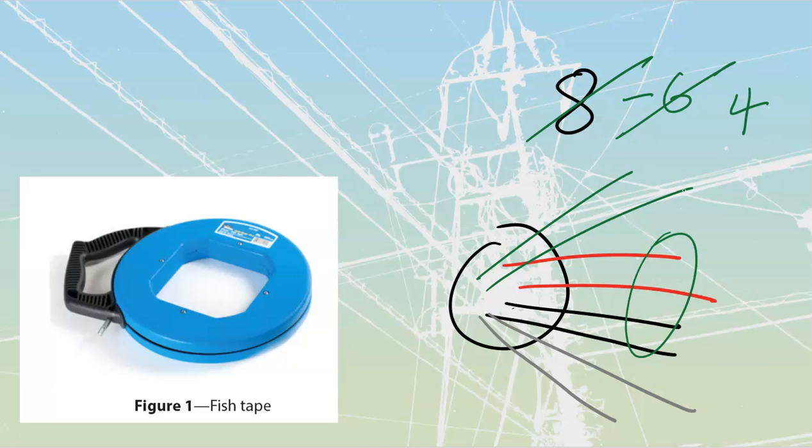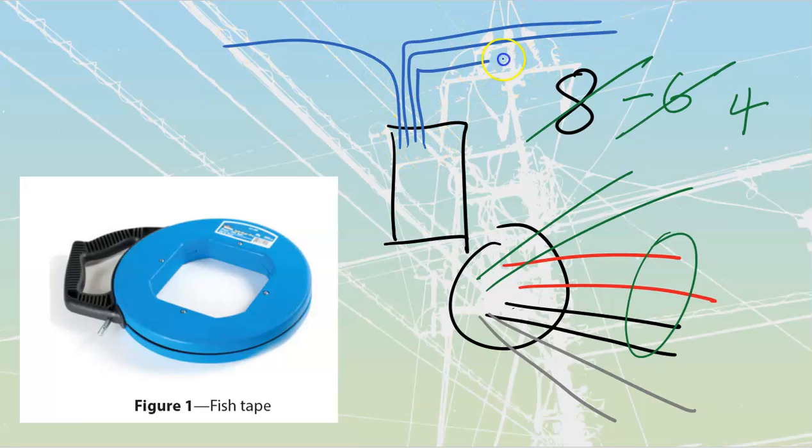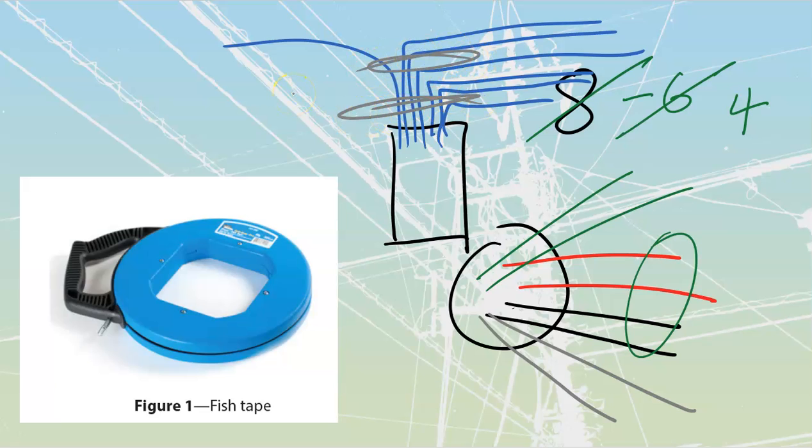There's a couple of other times that we do need to also derate, based upon contact. This is where I've got them all inside of either a cable or inside of a conduit. That's easy to understand. But what about in cases like this? And you have all done this before, where you're wiring up a suite or something like that, and the only place to bring your cables down is in from the top. And so you have all of these cables that are just being brought down and they're being stacked really close together, and you've got a couple of scab pieces of lumber that are going to be behind that.